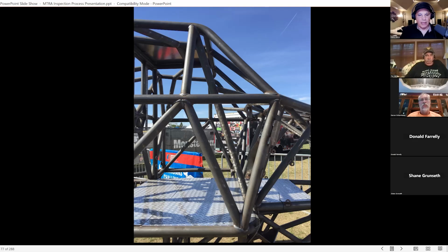That's a critical bar right there, that angled bar going up to the cab corner where the A pillar meets the roof. That secondary bar was something that got added within the last few years. It's really important because, as you're visualizing this, you've got this triangulation, and you're looking for these triangles, but you're looking at it longitudinally.